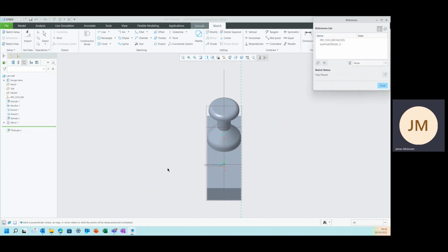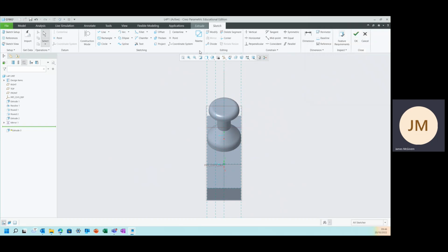Right click, references. Get that edge there. That edge there. That edge there. The center, so I can put the hole right in here. And I could also select that edge there. Close that. The circle is going to allow me to make a hole here. About that size. So that is 8. I'll make that 8. That hole diameter 8.